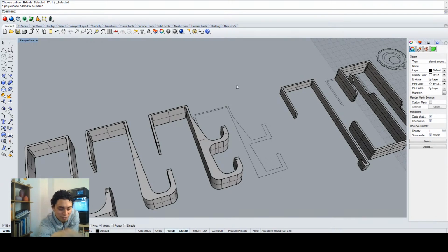If you're trying to render it out, smaller radii will really make the part stand out and be more believable, because ultimately there's really no industrial process that can create perfectly flat parts. And 3D printing is no different. In this case, it's not only for you to be able to print it better, but also to dissipate a little bit of the stresses that will be created in each of these corners as the part nests against the door, right?